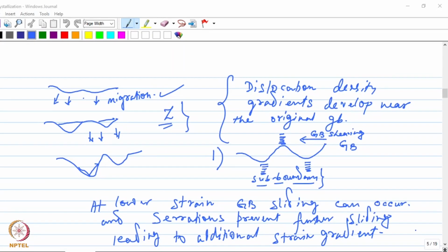So to summarize these two forms of dynamic recrystallization, DDRX and CDRX, we can say that the DDRX process occurs in conditions when dislocations can accumulate to generate a gradient in dislocation density or strain energy across the grain boundaries to form the nucleus. This process will be more dominant in materials having low stacking fault energy, because in such materials dislocations can accumulate.